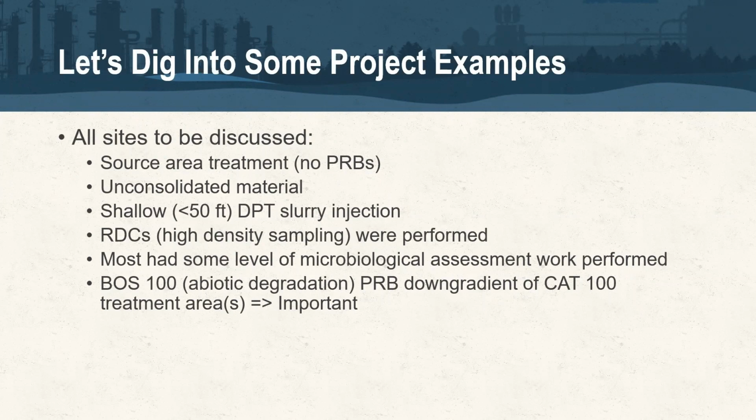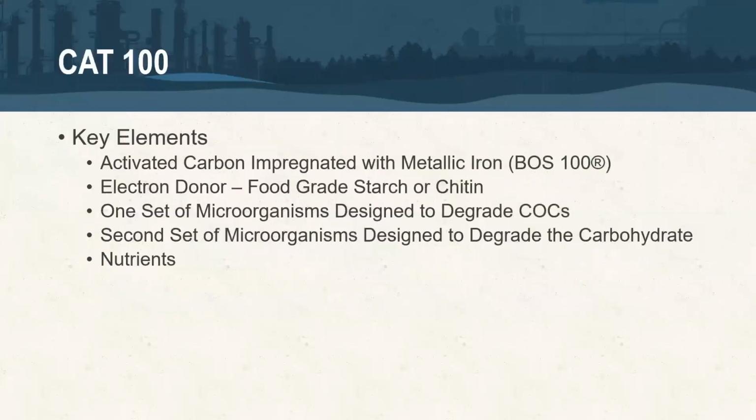And I think that's very important. For all ERD technologies, we want to make sure we've got something down there to capture, because regardless of what you're doing from an ERD standpoint, it's never going to be 100% complete. You're always going to have some, say, cis vinyl bleeding out of these areas, especially when we're talking about milligram per liter type starting concentrations. We want to make sure we've got something down there as a fail-safe.